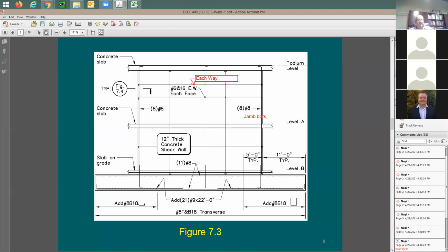Now, you understand that the force is going to be coming like this from the seismic, from the earthquake. Same thing here also, you're going to have another force, meaning that your moment is going to be in this direction here. So this side is going to be compression and this side is going to be tension. If you remember in beams, you'd like to put the rebars all the way in the tension side. So I said, okay, let me put here number 8 for tension side. And this is going to be the most effective location of the rebars when you put at the end.